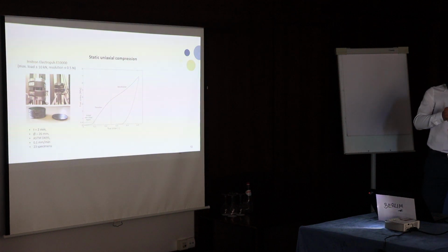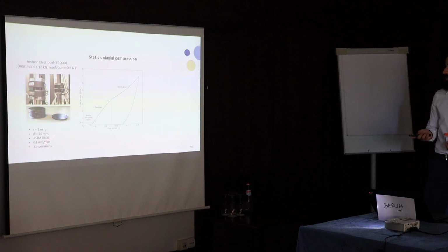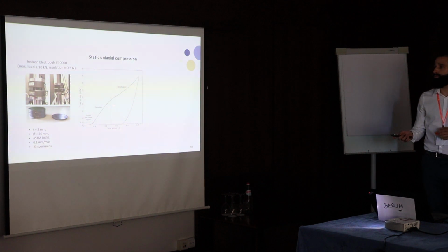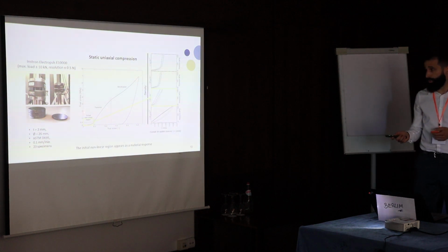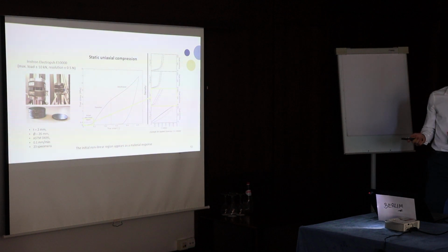So we had disc-shaped specimens. We tested them in the out-of-plane direction under static compression loading, and we also tried to stack them in a pile of 6 sheets. And this is the response that we got. It didn't change. There is no difference between the single-layer specimens or stack of specimens. So this is the stress-strain curve. We see an initial linear region, a transition, and then the concavity turns upward, which probably corresponds to the densification of the material.